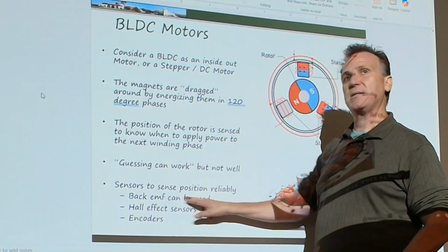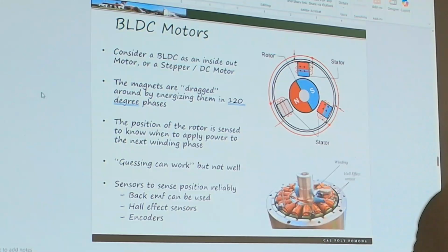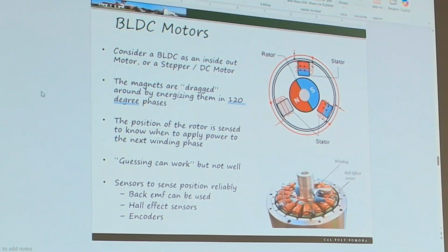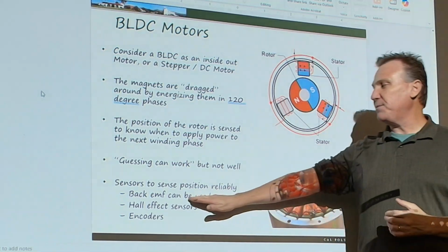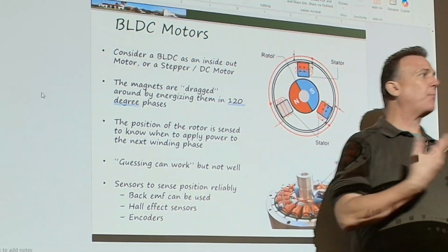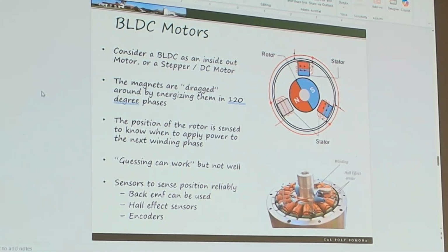Because this is continuous. This is discrete. And the problem with something that's discrete is it's only this or that. It's 1 of 2 possible states, right? I can't measure if I'm in between states. It's either on or it's off. But the back EMF, I can have a better quality one. Some Hall effects, I can actually look at proportional voltages as opposed to just on-off, depending on the Hall effect that I'm using. But encoders, they're digital, they're not subjected to the analog problems.